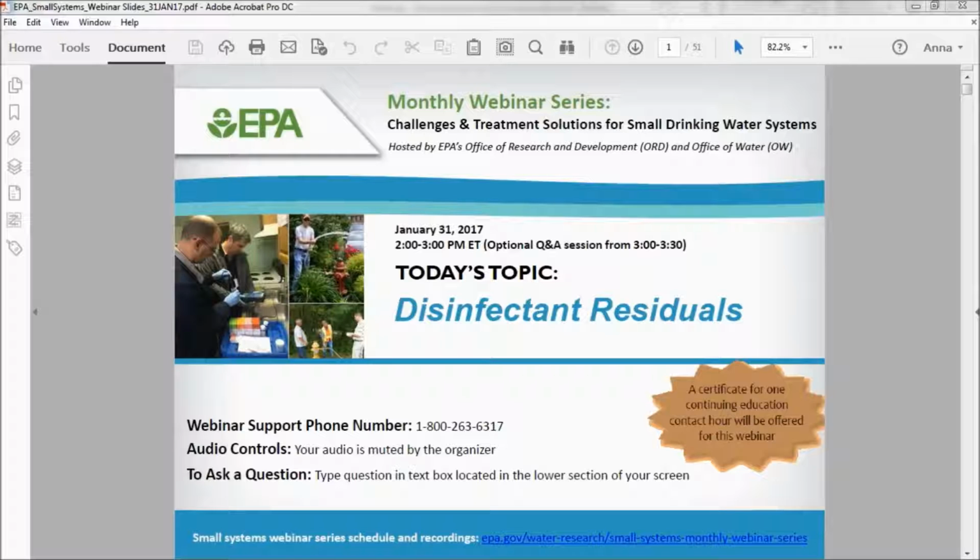I would recommend if you're in the low range, which is less than 2 milligrams per liter, using that range, because you're going to get more precise results. It will give you a reading out to 100th of a milligram per liter. The trouble when you use the high range method and you actually have a lower residual, you just don't get the precision, and it's likely less accurate. Okay, great. Thanks, Matt.